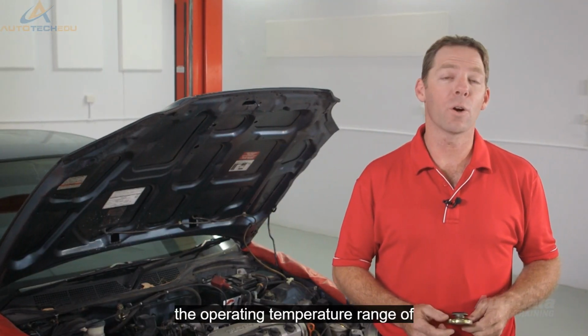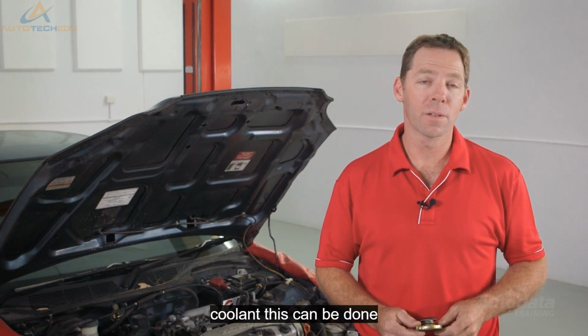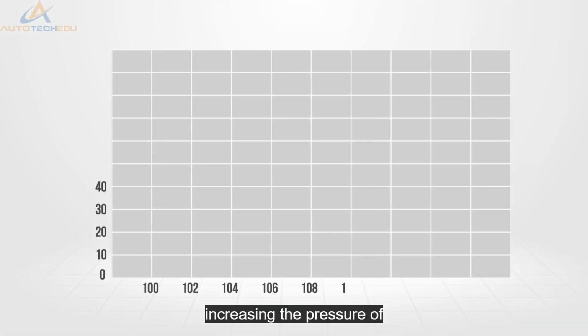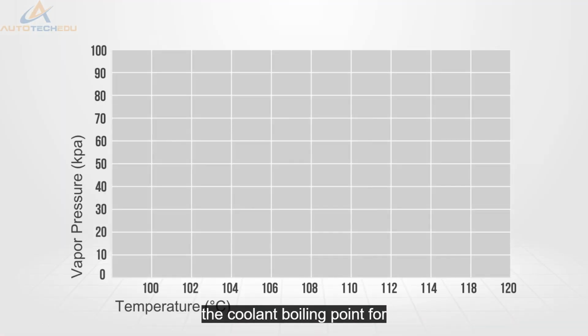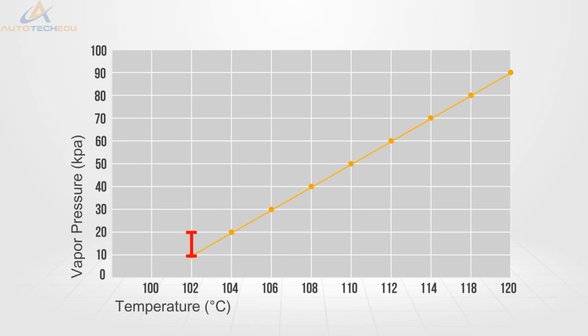Another way to widen the operating temperature range of the engine is to raise the boiling point of the coolant. This can be done with a radiator cap. Increasing the pressure of the cooling system will raise the coolant's boiling point. For every 10 kPa of pressure increase over atmospheric, which is about 103 kPa at sea level, the coolant's boiling point will be raised by 2 degrees Celsius.